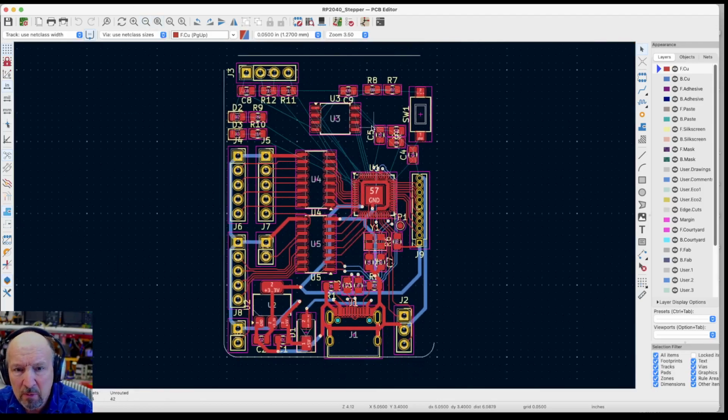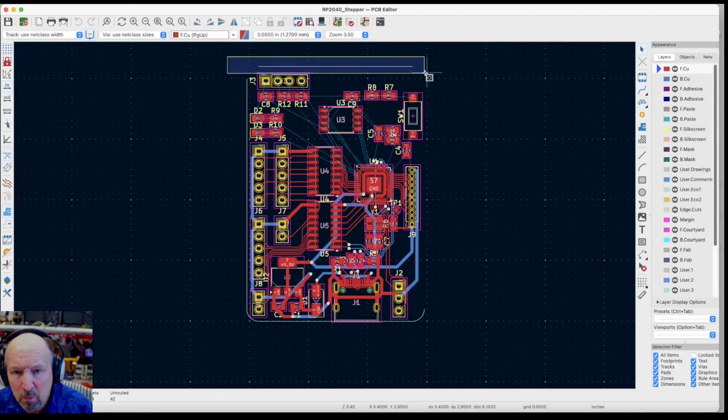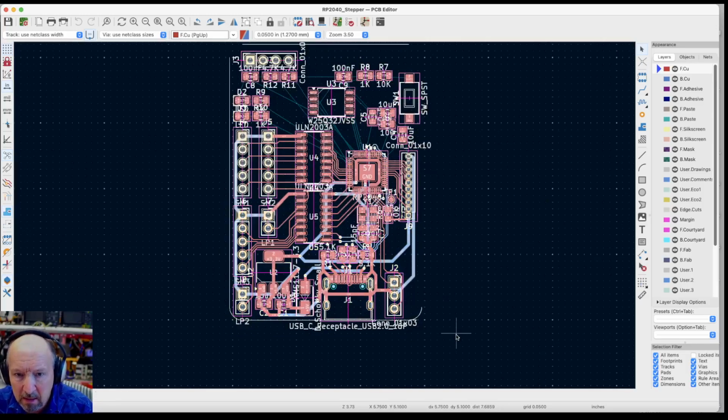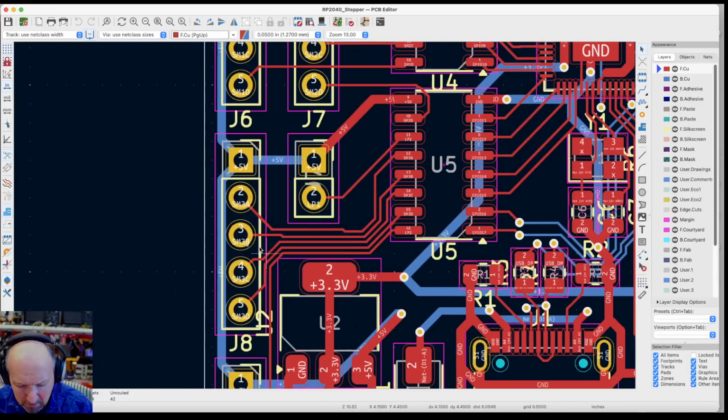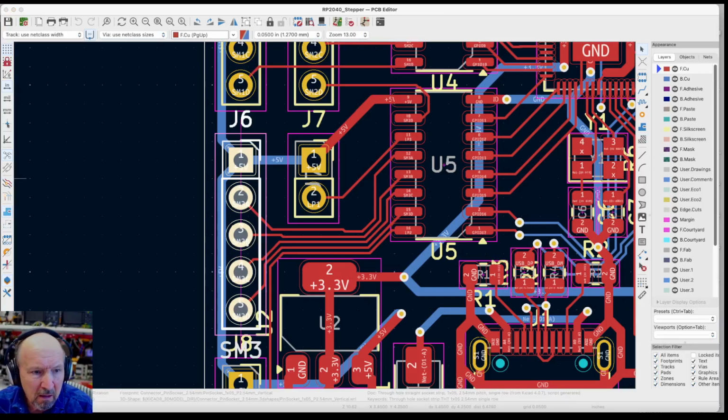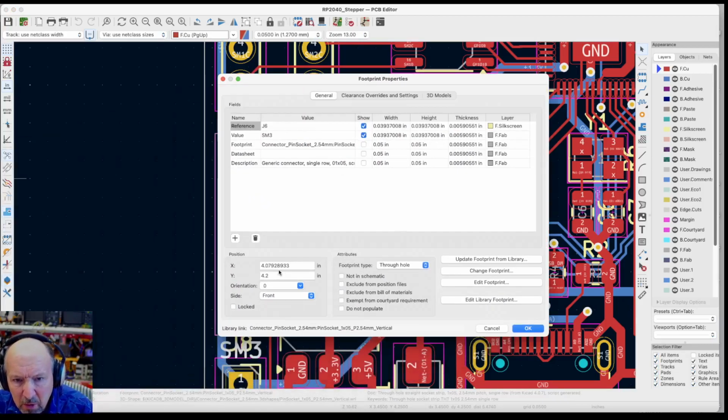Now, if I zoom into the whole board and swipe and select the whole thing again, what I need to do is move it by that fractional amount so I get it back on a snap point. Then I can move it exactly where I want it. I actually looked at the location of this connector, and it's also at that 0.7928933. So what I want to do is subtract that off of everything on the board.